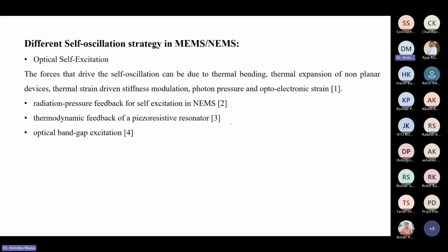You can extend this work to a multi degrees of freedom system or a continuous system. You can use different control strategies. Here only the stiffness switching control strategy has been used. There may be other control strategies you can develop. Also, you can develop some adaptive control strategy where you do not have to change the system parameter when you are changing the control gain. It automatically changes the control gain value. So there are several scopes for that.